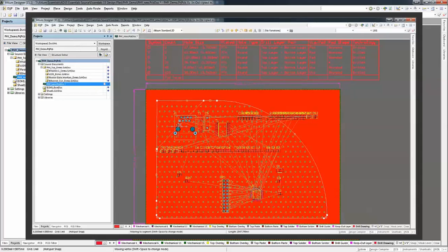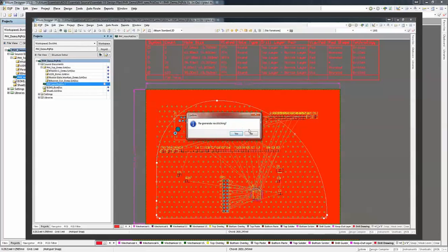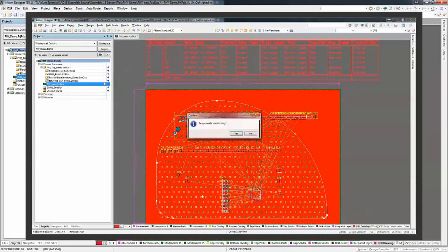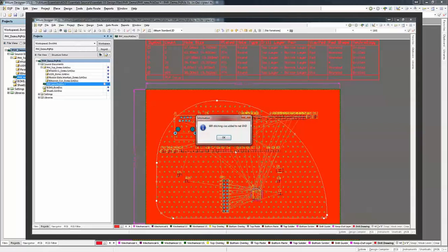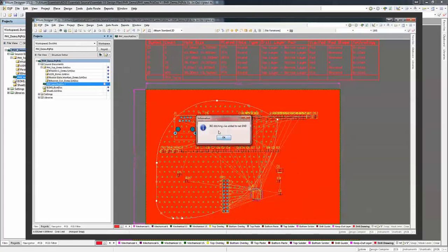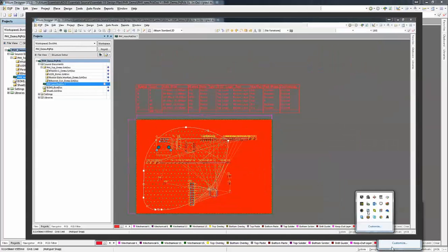I can also then go ahead and change the size as well as the shape of the via stitching as a group. I can say I want it to be a circular arc. I can change the chamfer. I can drag it all the way in as well if I want to. I can change or add vertices as well to this via stitching group also. This is a very good way to actually manage your via stitch. You don't have to place them all one by one. All you gotta do is just place them in an array and change the size of the array when need be.